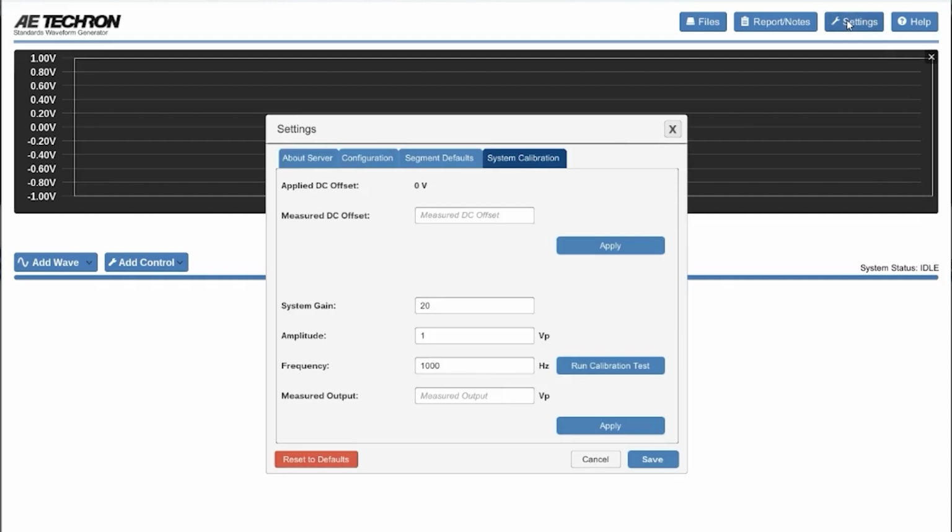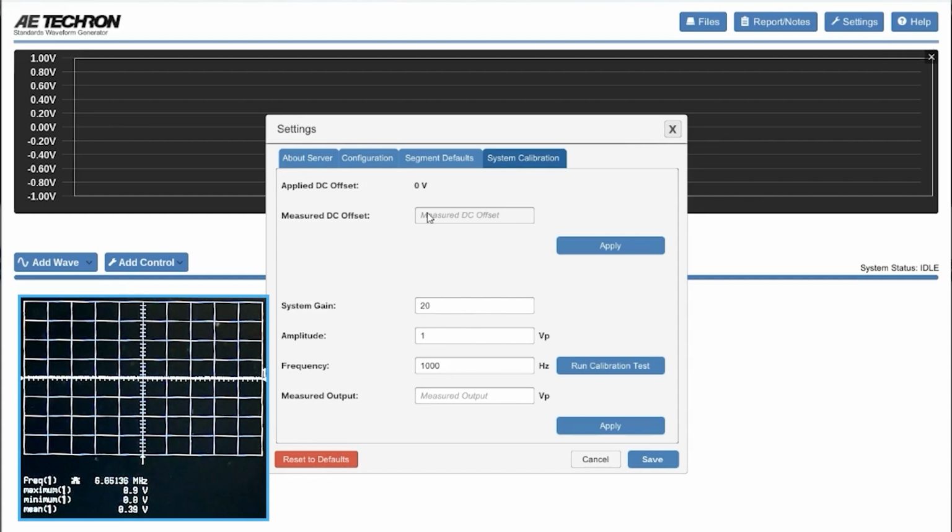The first step in the calibration process is to set the DC offset. In this example, we are measuring frequency, but this is not necessary. Set your oscilloscope to measure the maximum amplitude and the mean or average amplitude. If your oscilloscope does not have a method for measuring mean amplitude directly, you can substitute this for calculating the difference between maximum and minimum amplitudes by hand. You will likely see some amount of noise in the system. For our setup with no signal, we are seeing a mean amplitude of 390 millivolts or 0.39 volts.